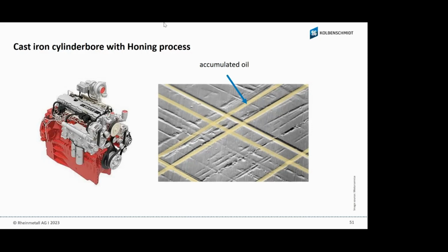You see, we need the scratching marks, and as I said before, these have a clamping effect for the oil, and the oil can drop down to the oil pan in this groove. It is important that these scratching marks from the honing process are a completely continuous line, and do not stop in between and start at another point.